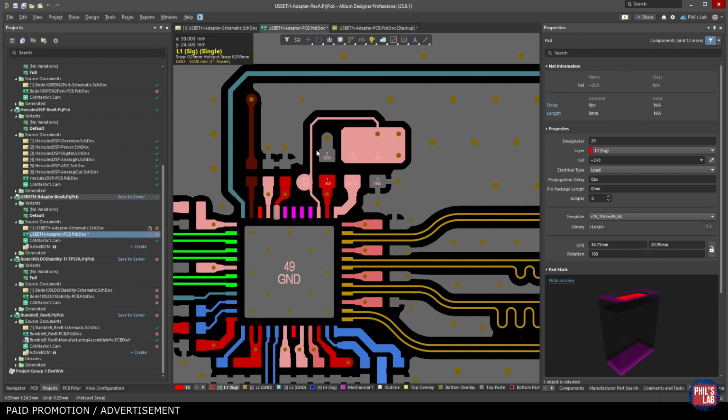Rather than generating Gerber files, which don't contain terribly much information, they are essentially just layer information for the copper layers and silk and solder mask layers, we want to include some other information as well, such as net names. We might want to include this layer and build-up information that we just saw. And for that, the preferred, very easy to use data format is the ODB++ format. You may have used that before to get your PCBs manufactured and assembled. The ODB++ format contains far more information than just the plain Gerber files. Pretty much any ECAD tool should be able to export this format, so it's very widely available and can be used very easily with HyperLynx.